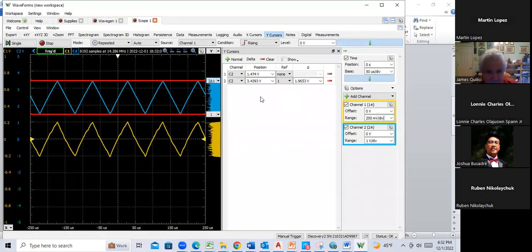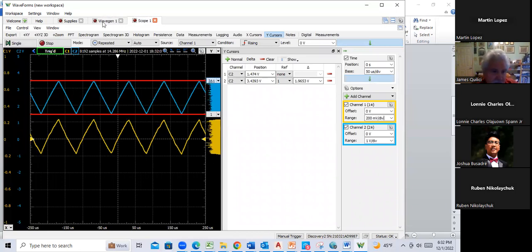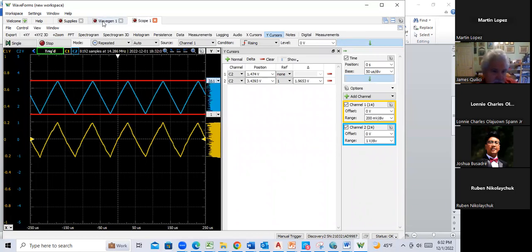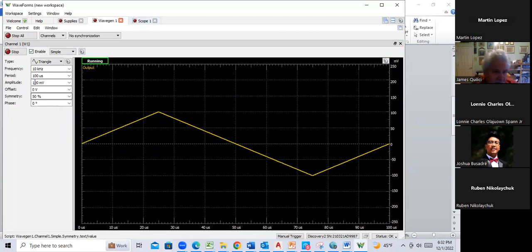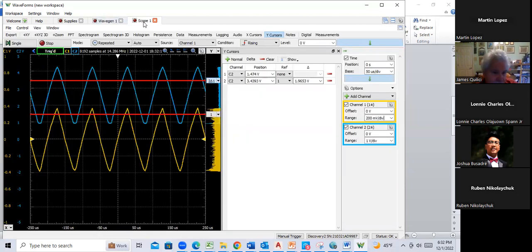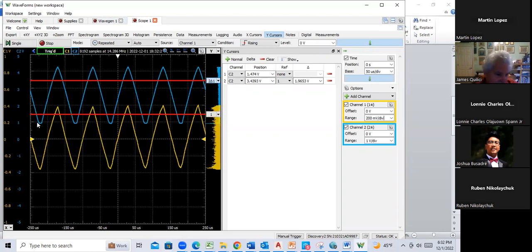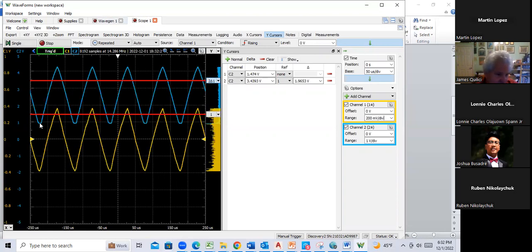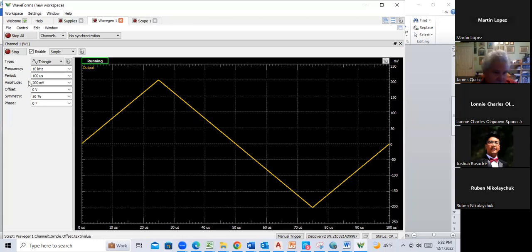So what I can do is increase my amplitude a little bit. The easiest thing to do is just bring it up a significant amount. Because we only have a 5-volt supply, we're not going to have a tremendous dynamic range. Mine bottoms out at around 0.9, but it hasn't clipped at the top. I'm going to bring that up even higher on wave gen. I'll put it at 0.5 volts.